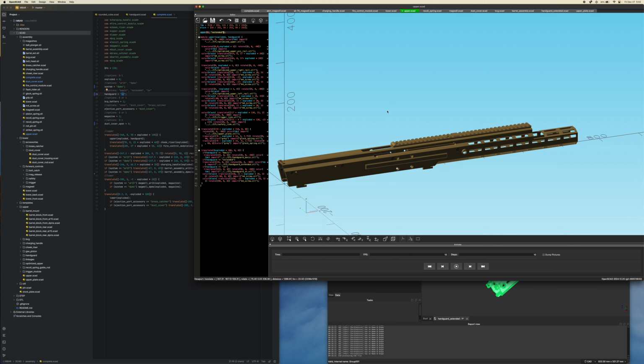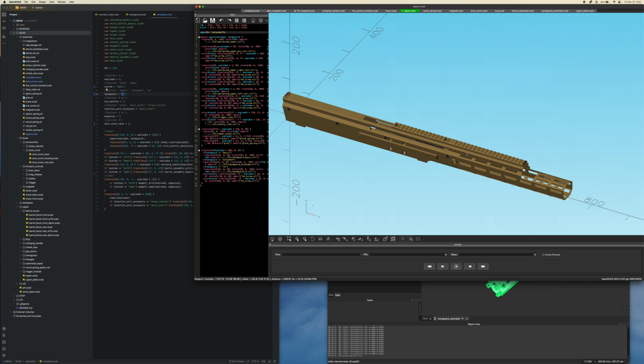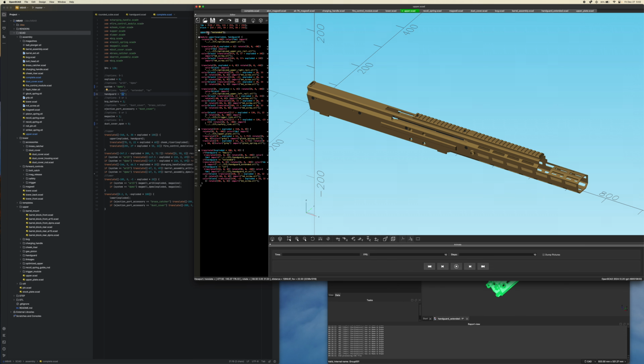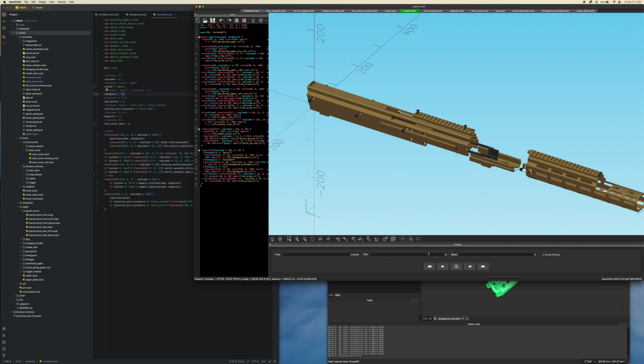The other cool thing is I can also animate this thing blowing up. To do that, I just switch our exploded variable to $t, and then I start this at 0, and do 10 steps at 10 FPS. Once I click play, you'll see that time will loop from 0 to 1, taking steps of 10 at about 10 FPS. I don't think that's actually 10 FPS. It's a little slow, but that's basically how that works. I'm going to revert this.